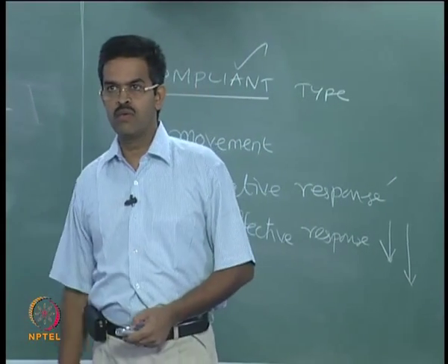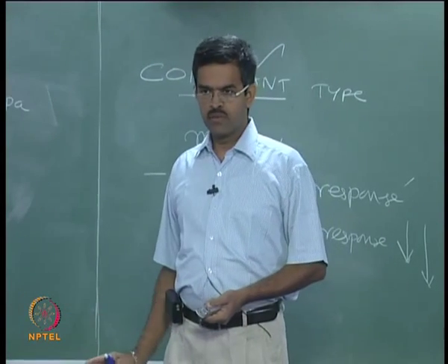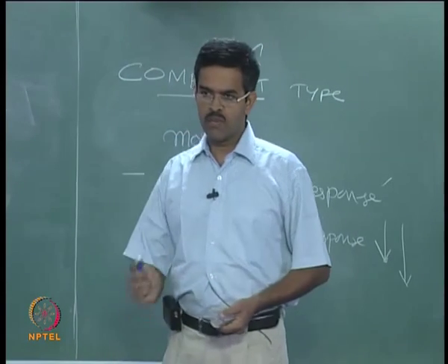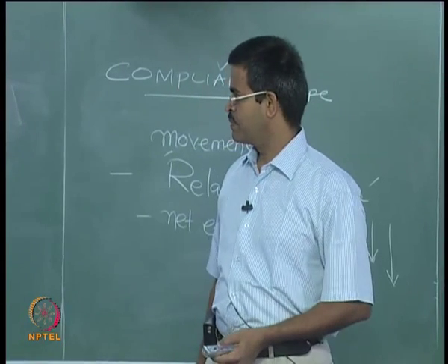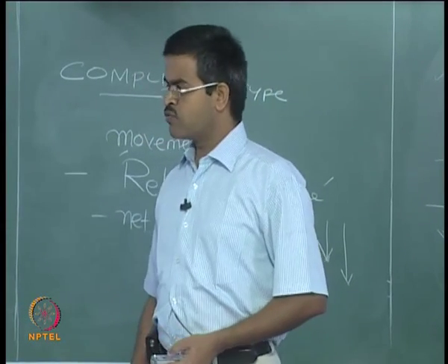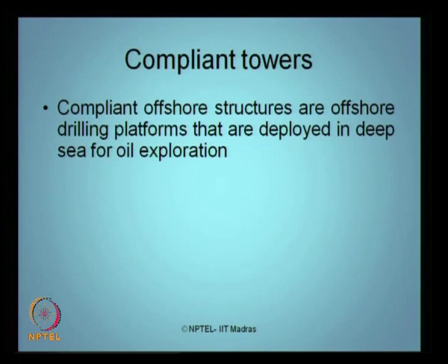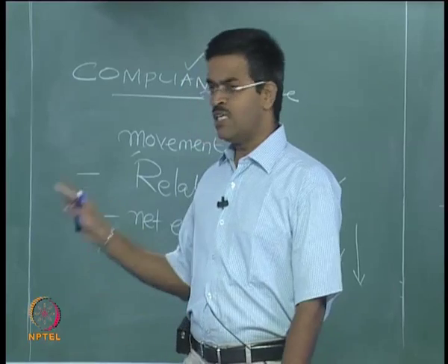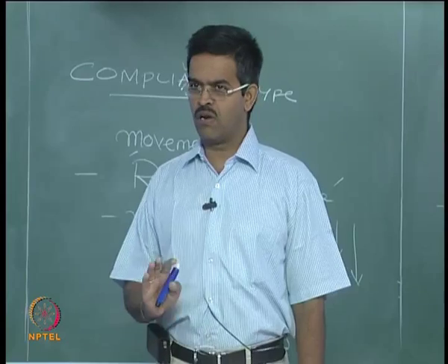Let us move forward. Compliancy means movement. So, the tower moves. The term compliancy stands for moving. So, compliant offshore towers are actually offshore drilling platforms that are deployed in deep sea for oil exploration essentially, not for production. Remember, they are meant for exploration, but of course exceptions do exist. Not always is every platform only for exploration, you can also use it for production as well. For example, TLP, for example spar, but essentially they have been initially designed for exploratory drilling only.